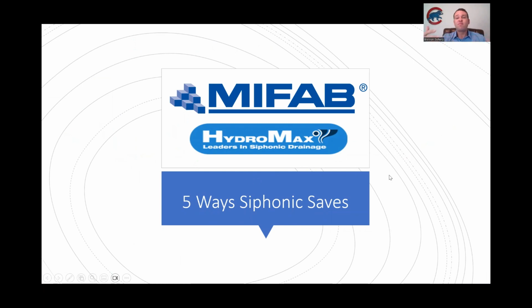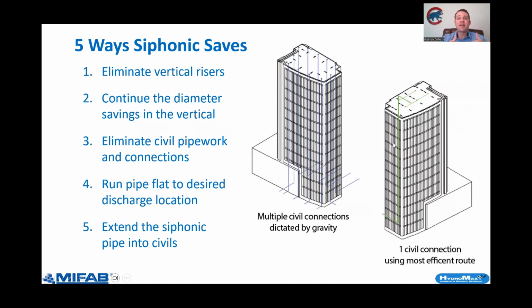Taking a look at some real life project examples and just really how you can get the most out of siphonic. One, here's our list side by side, but high rise is another great example where we can see cost savings, anything over really 5 stories, right? Thought being that on most of our designs, we're having our risers on the outside of the building because sloping to the center doesn't make sense. We need more building height. And once we get to the bottom, we're gonna have to slope to get out to civil. So that's a poor design.